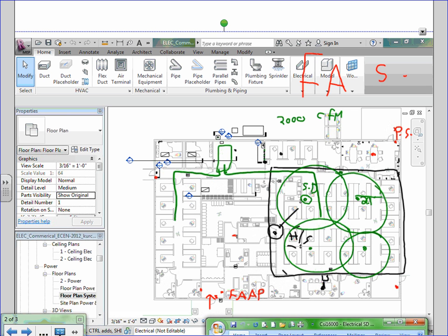This specific building has a plenum return. So there is a return duct, but essentially all it does is come off of the air handling unit and basically just punch into this corridor right here. And then there's ceiling space throughout the entire space.